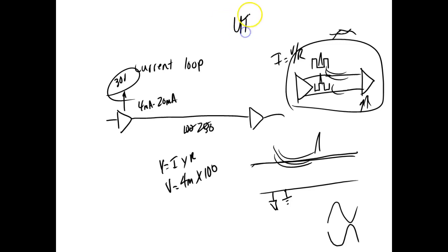We got UTP and we got STP. Y'all know what those are? Yeah, shielded and unshielded. In industry, they'll add a second layer. They'll put a shield around it, and that way it'll run. Ethernet is a differential interface. USB is a differential interface. So we can run these USB cables a pretty good distance without worrying about picking up stuff.